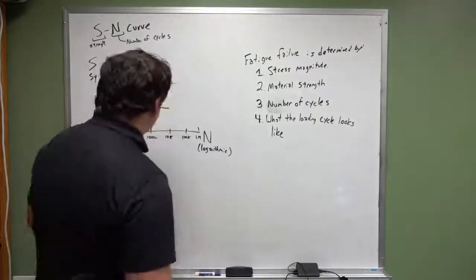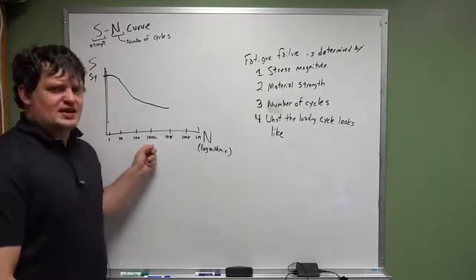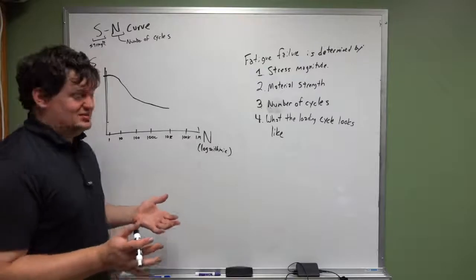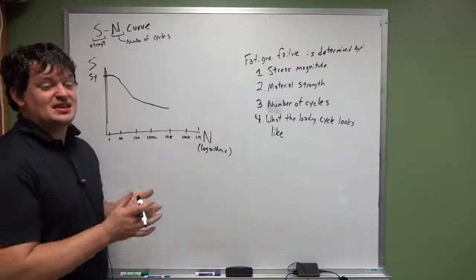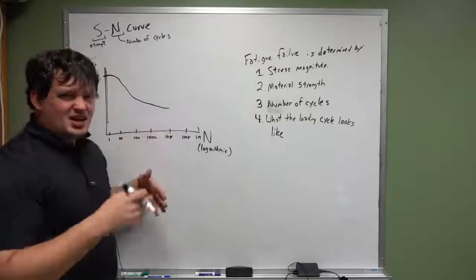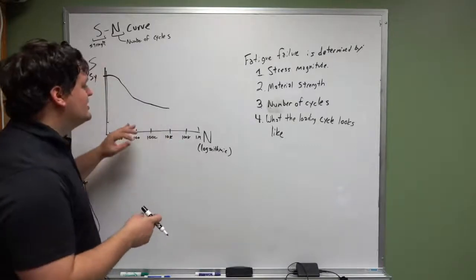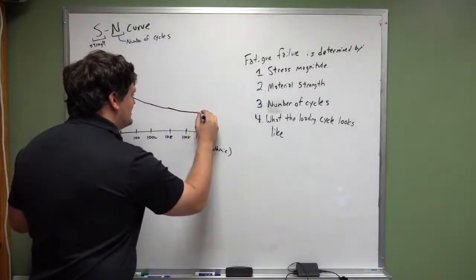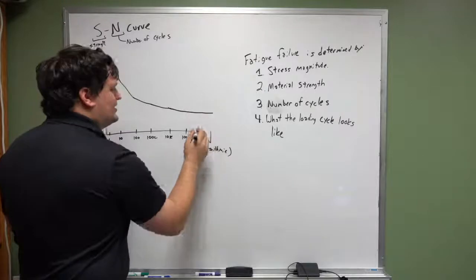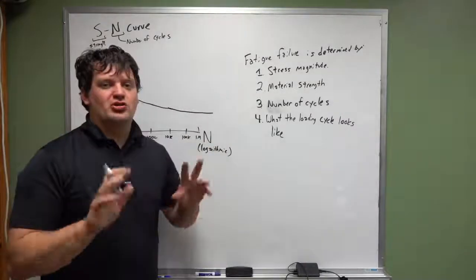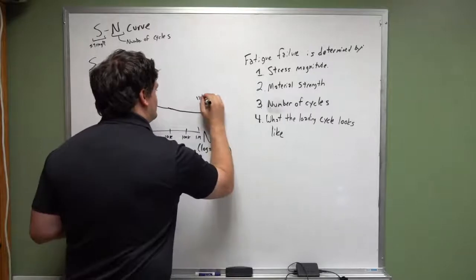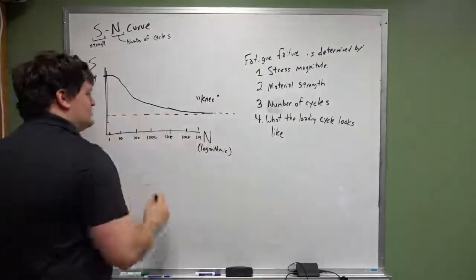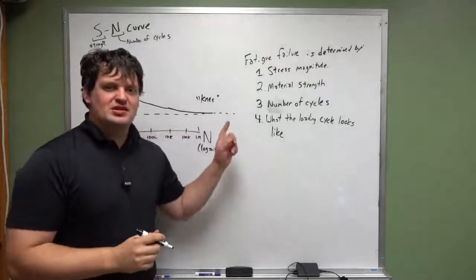Hopefully. So what we have here is the difference between 1,000 loads and 10,000 loads. The way that a material sees it actually isn't that big. Like for us, 1,000 to 10,000 is huge, but for the material it's not that big of a deal. And what you'll see is after about 10,000, 100,000, a million, after about this point, it experiences what the book calls a knee. And what that is, is that the strength never actually reduces beyond that value ever again.